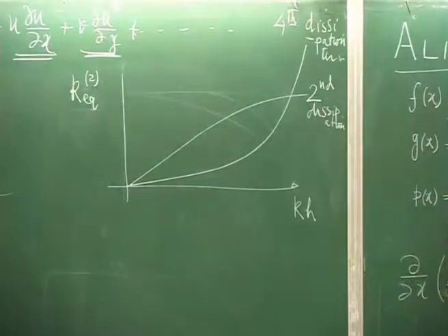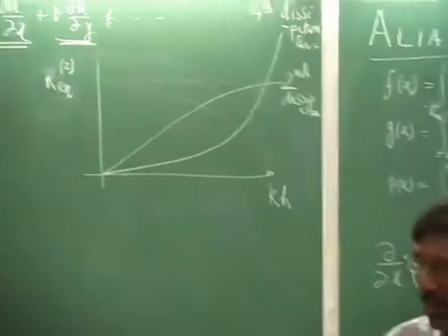I would prefer a fourth dissipation term. Why? For two reasons. Because we said that this dissipation is added to control numerical instabilities, and numerical instabilities always occur at high wave number. That is what we discussed when we were talking about the multigrid method also. That was one of your questions: why in restriction you smooth and in prolongation you don't.